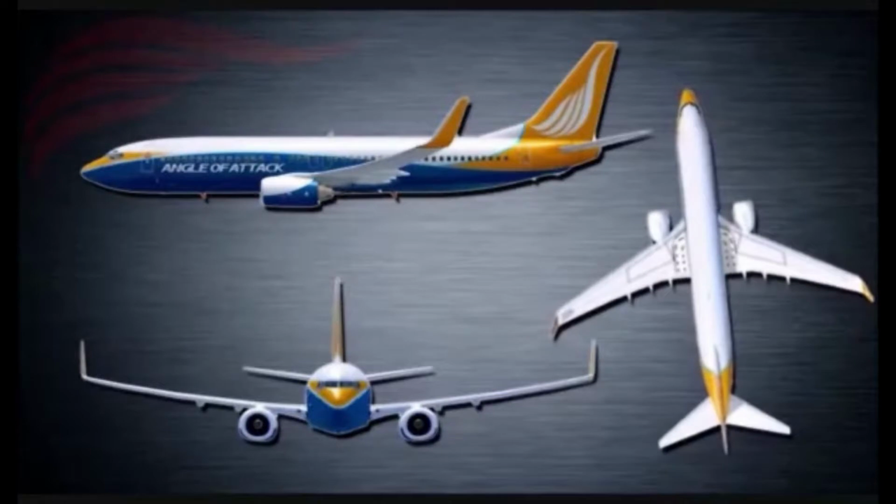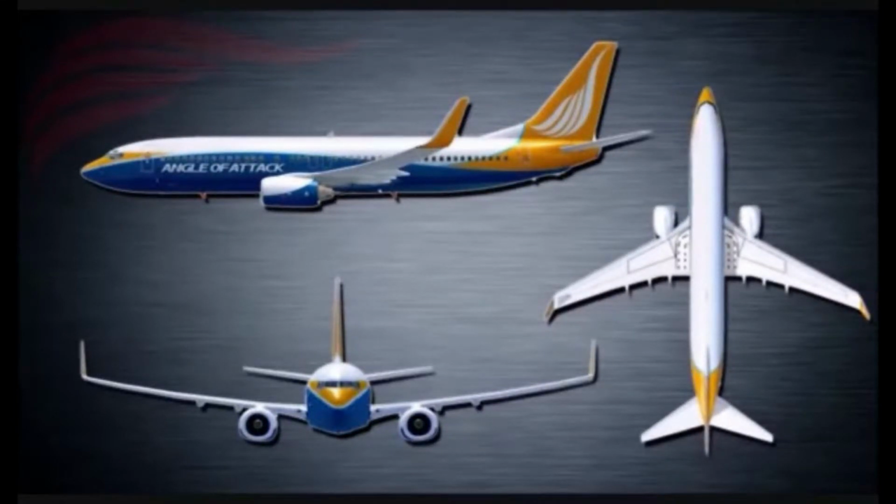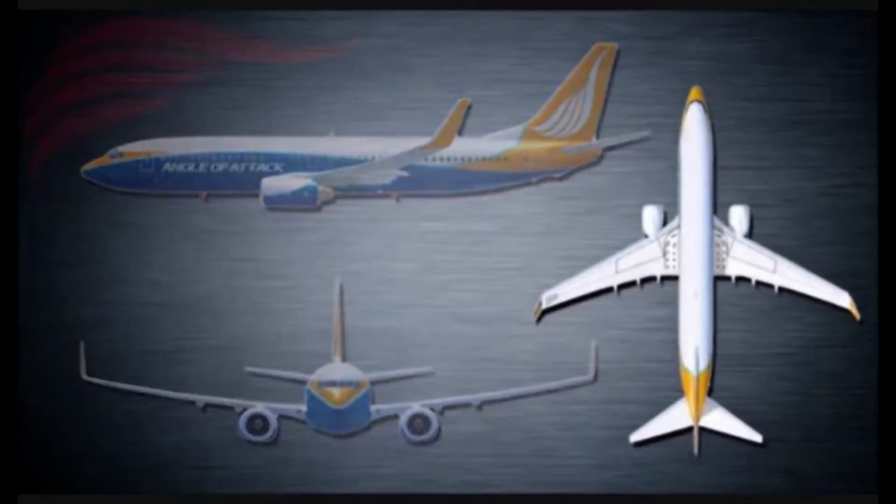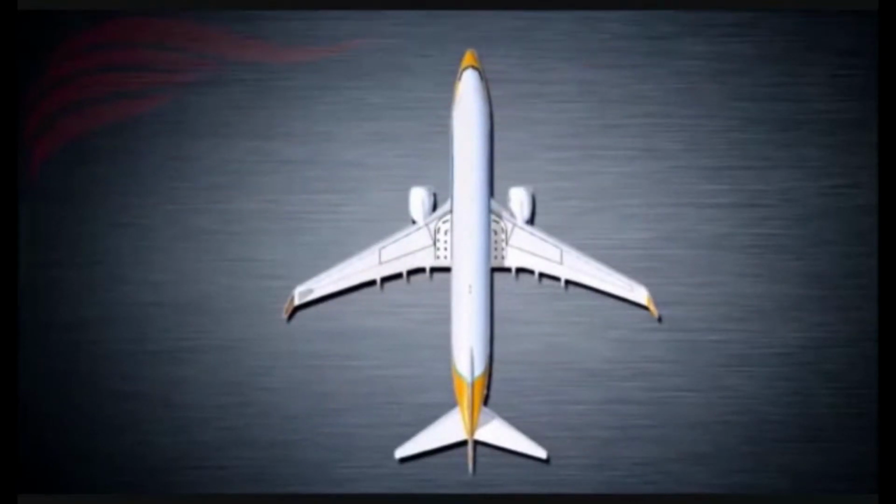To achieve these movements around the aircraft's axes, flight controls are employed. There are two groups of flight controls: primary and secondary. The primary flight control surfaces and their direct effects are elevators, change in pitch; ailerons, change in roll; and rudder, change in yaw. An aircraft is free to rotate within the three axes and will always turn about its CG, or center of gravity. The tendency to do this is known as a turning moment.